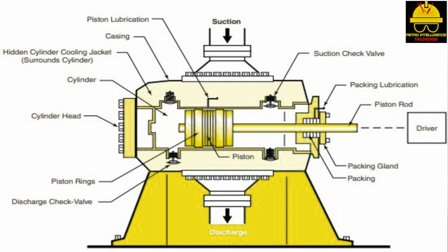The back-and-forth motion incorporated by a reciprocating compressor pulls gas in on the suction or intake stroke and discharges it on the other. Spring-loaded suction and discharge valves work automatically as the piston moves up and down in the cylinder chamber. The basic parts of a reciprocating piston compressor are shown in picture. Reciprocating piston compressor design varies from model to model. These variations usually occur in the total number of cylinders and in the arrangement of the suction and discharge lines.